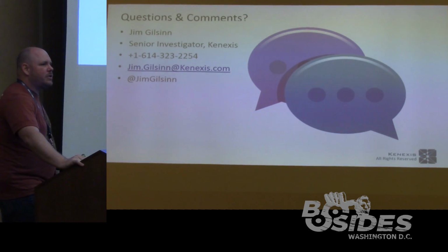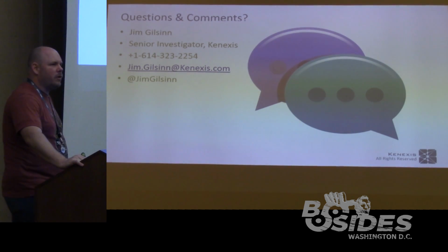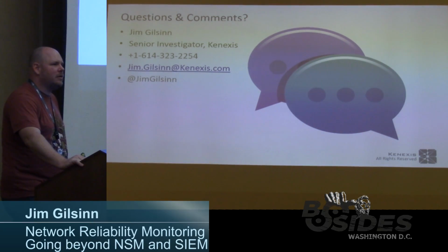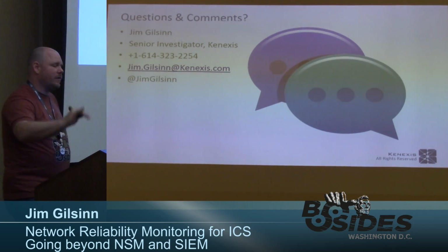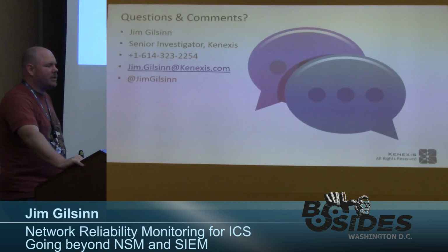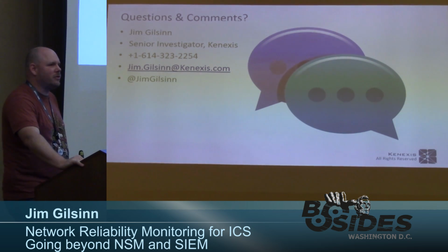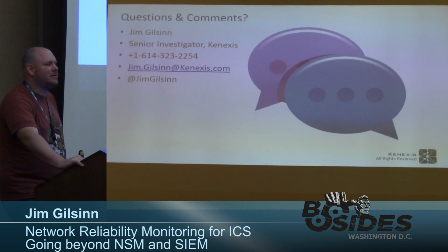where they did not prevent the operators from loading web pages and plugging in their devices into the operator stations. So if they didn't have their firewall locked down to not allow web traffic through, then what happens a lot of times is they will introduce stuff by visiting whatever they go to. And it's sad to say, but it's not uncommon to see porn on HMIs in industrial control systems or other weird places that people have visited.